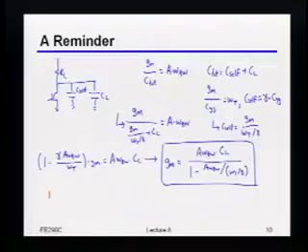So why did I spend this much time deriving this thing? Well, it gives you some very nice intuition for how much power it takes to get a certain bandwidth, or really a certain gain bandwidth. Notice that the gain bandwidth on the bottom is getting normalized by the intrinsic gain bandwidth of the device, right? In particular, when A omega bandwidth is equal to omega t over gamma, meaning this whole term is 1, well, 1 minus 1 is 0, and 1 over 0 means it's infinite, right? Forget it, not going to happen.